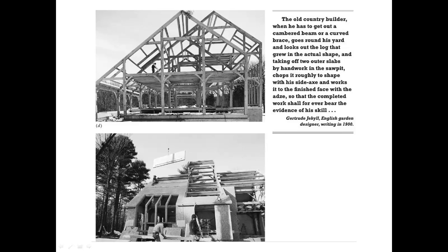And on this bottom photograph, you'll actually see these structural insulated panels being applied to the top of the roof and the walls to provide a thermally unbroken insulation skin for the outside of the building. So from that standpoint, they become very well insulated, although more expensive than your normal light frame construction.